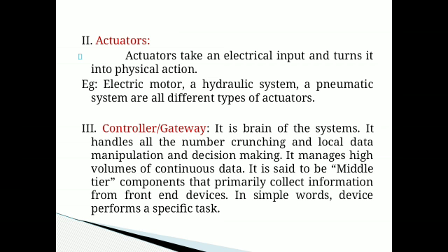Right? So here sensors will act like an input device, whereas actuators will act like an output device. Actuators take an electrical input and turn it into a physical action. Reverse concept of sensors actually. In sensors, physical data is converted to an electrical signal. In actuators, electrical input is converted to a physical action. Examples: electric motor, hydraulic system, pneumatic system. These are all different types of actuators.